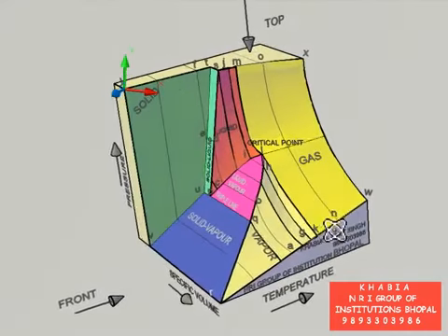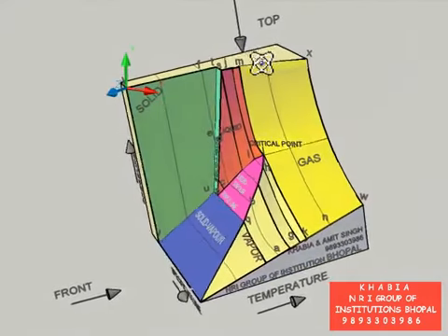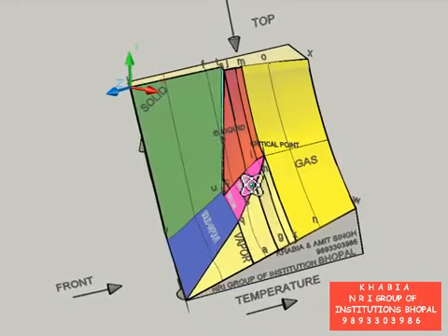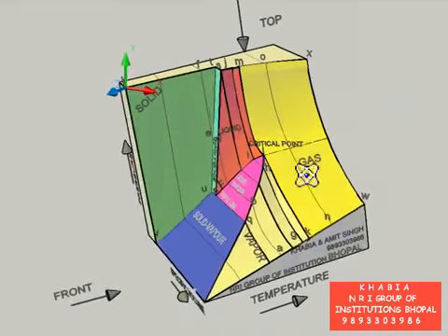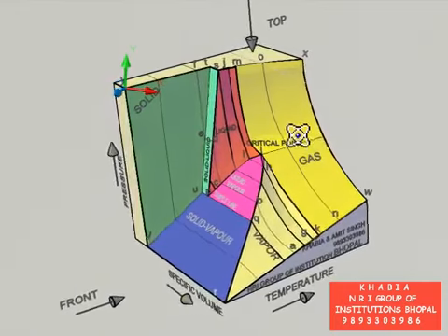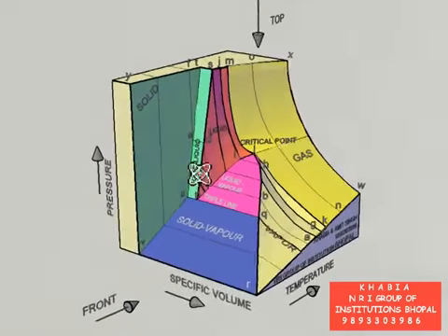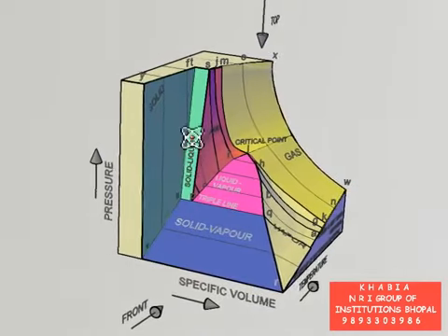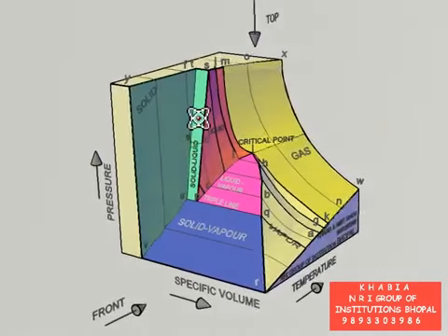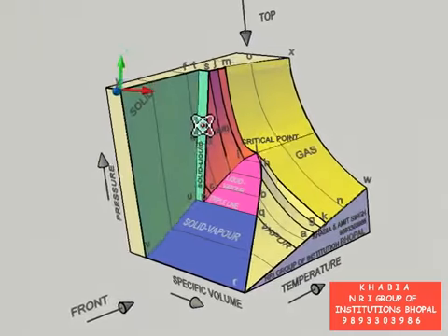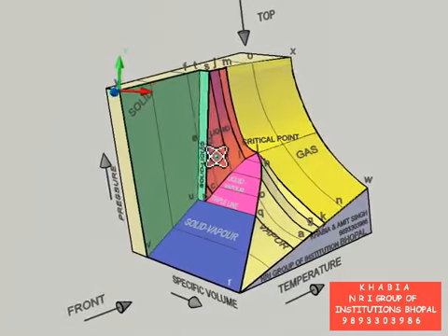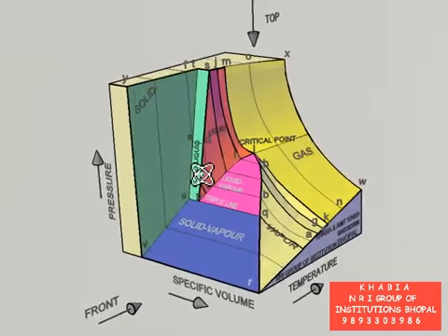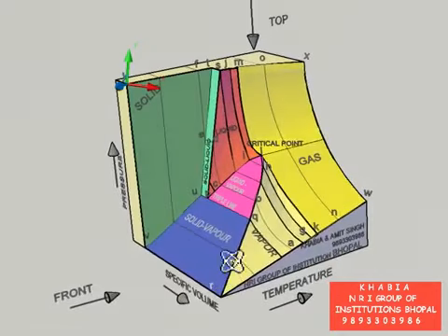The yellow colored surface KNWXOMLK indicates various possible equilibrium states of the pure substance in gaseous state. The light blue colored phase PSTU indicates various possible equilibrium states of the pure substance when it is in two-phase solid liquid region.